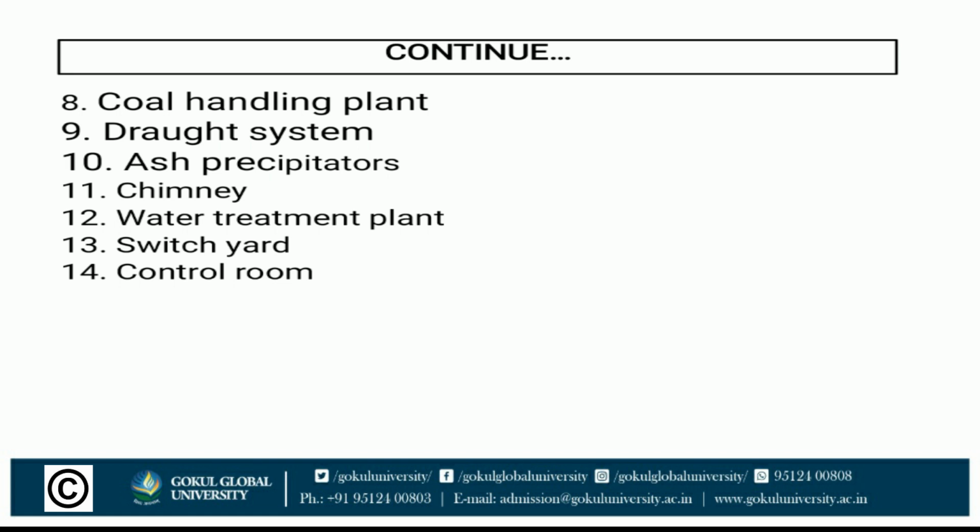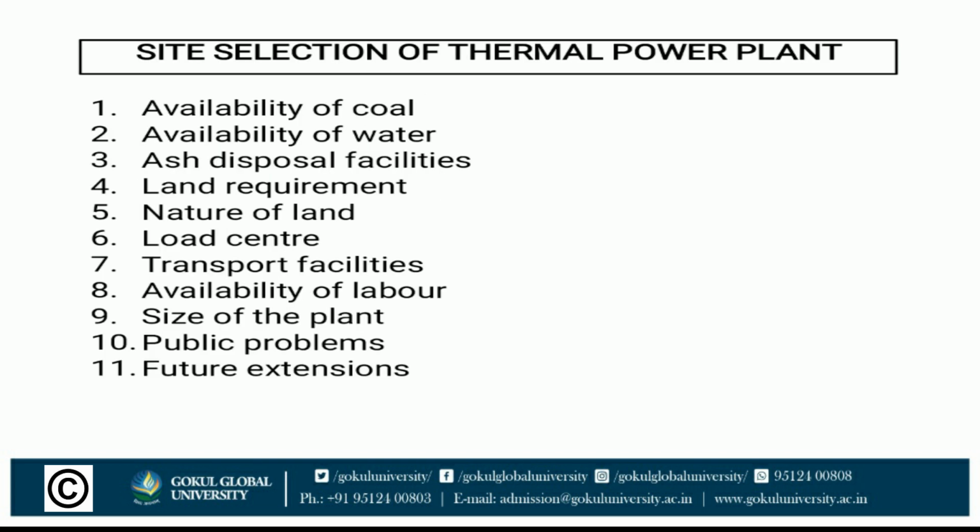And last and final, control room. The control room houses all the necessary measuring instruments for each panel of generator, means alternator, and feeder, synchronizing gear, protective gear, automatic voltage regulator, communication arrangement, etc. The performance of all the plant equipment is constantly monitored here with the help of sophisticated instrumentation and controllers.